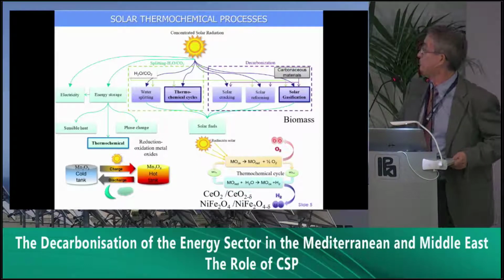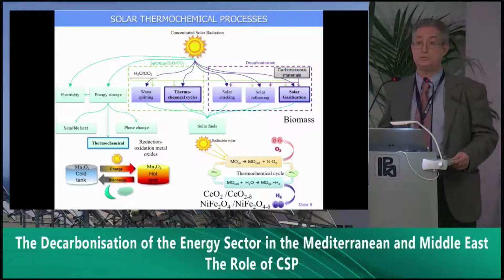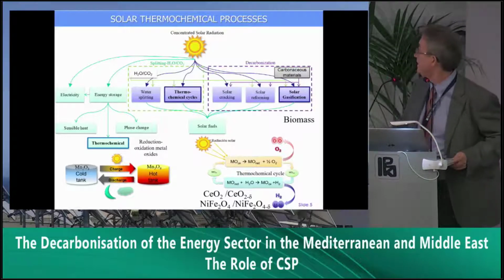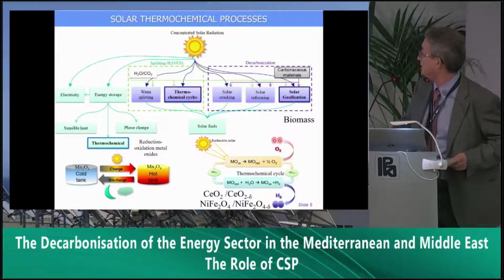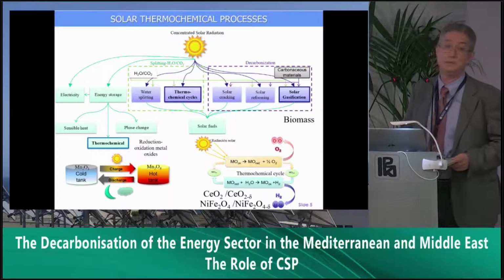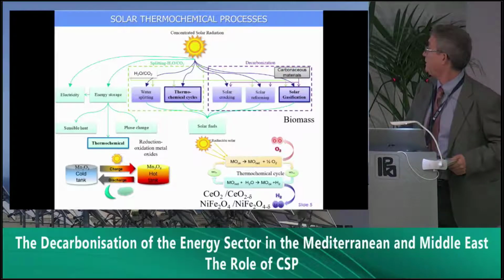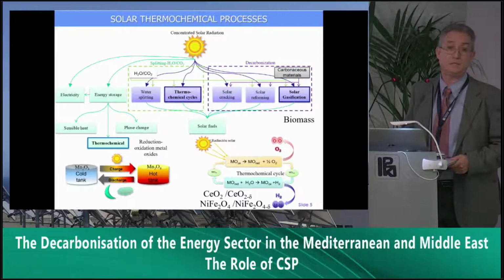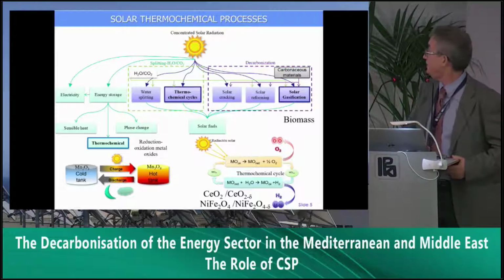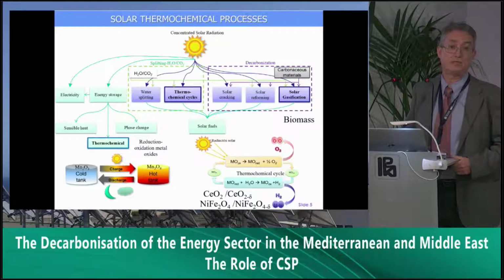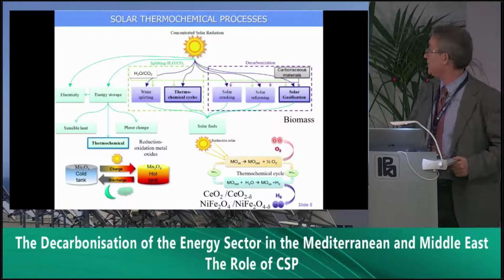And finally, we have the solution of using also reversible reactions to try to produce some fuels. In the case, for example, of hydrogen, as you see here, normally we use a typical metal oxide, which is quite simple chemistry, and we reduce thermally this metal oxide, releasing some oxygen at very high temperature, and then we undergo the second step, which is the oxidation of this material, for example, with steam, and try to regenerate the original material.